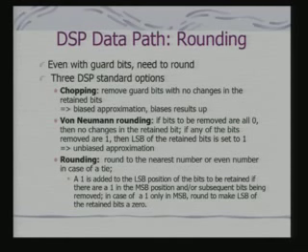The basic philosophy of rounding is to round to the nearest number, or to the even number in case of a tie. It is an approximation technique which has the minimum error bound. So, what happens here? A 1 is added to the LSB position of the bits to be retained if there is a 1 in the MSB position of the bits being removed and or subsequent bits have also 1s.